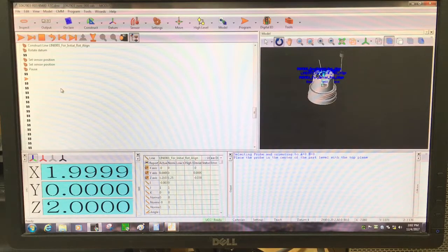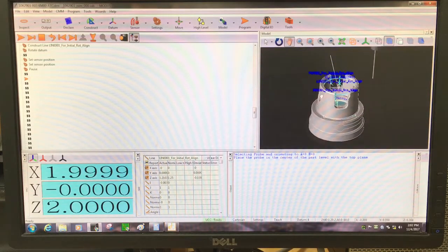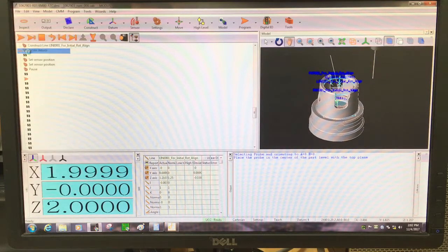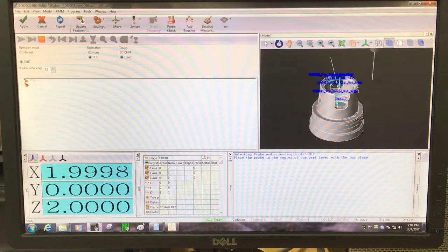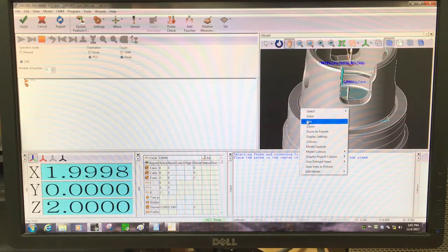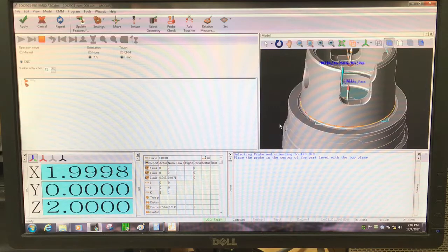Okay, in this video I'm going to go over a quick and simple way to construct a cone using a couple of circles. The cone feature doesn't always work under the inspect. Sometimes it causes the software to crash, so I always find it easier to just use circles. So I'm going to select just a circle near the taper. I'll just pick this one here arbitrarily.